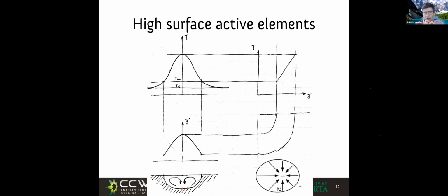So when I told you it's the same material, that's what they thought, because it is the same 304 stainless steel. But it wasn't exactly the same. There was a difference, of course, but the difference was within the specification. So in this case, we have high penetration. If you don't control in your case the oxygen through aluminum, or you don't control the amount of sulfur, you can have some days high penetration, sometimes low penetration.